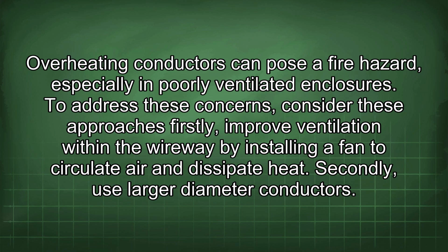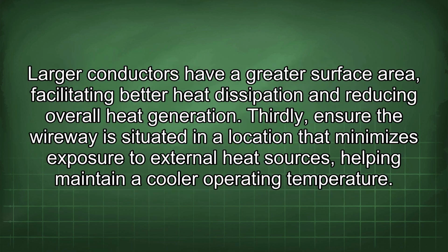To address these concerns, consider these approaches. Firstly, improve ventilation within the wireway by installing a fan to circulate air and dissipate heat. Secondly, use larger diameter conductors. Larger conductors have a greater surface area, facilitating better heat dissipation and reducing overall heat generation. Thirdly, ensure the wireway is situated in a location that minimizes exposure to external heat sources, helping maintain a cooler